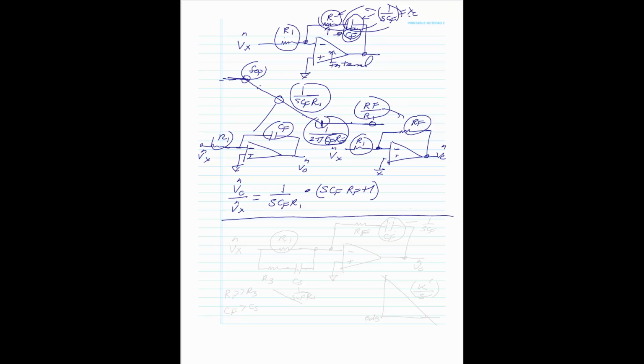The last circuit I want to discuss is voltage mode control, and we're going to do a lot on this. This circuit is very, very popular for, of course, voltage mode control. Just like we had before, we had two poles in the plant. I call the power stage, the converter, the buck, the boost, the buck boost, your plant. And we had two poles, and therefore we're going to need two zeros to cancel those two poles.